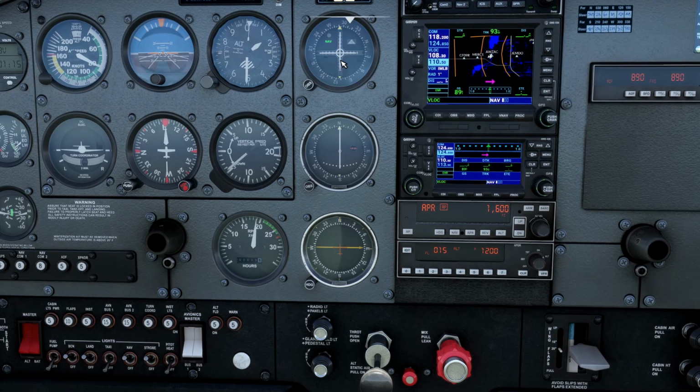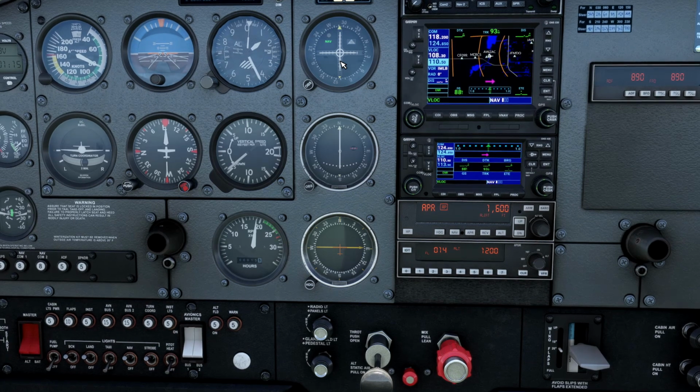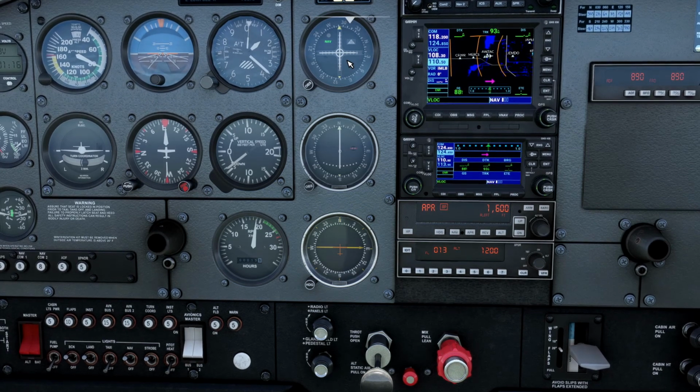As far as proper technique, you should disengage the autopilot no later than 200 feet above the ground, or the ILS decision height altitude, which is typically 200 feet. If you want to experiment with keeping it on later than that, what I found is that it will track the glide slope pretty well to about 100 feet, and then it kind of just comes down at about a 300 or 400 foot per minute rate after that. It actually does a pretty good job of tracking the localizer all the way to the ground.